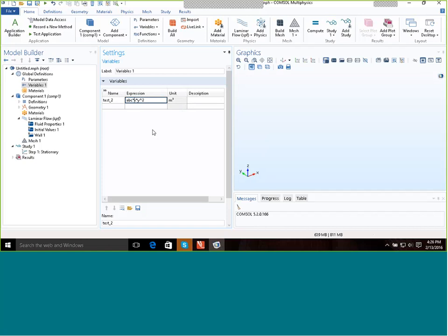Now, COMSOL is not going to know what ABC is unless I accidentally pick something that's an internal variable. And so what is it going to do? And you can see it gave this little orange color, which means COMSOL is confused, but it will keep going. It's kind of risky to keep going. You can hover your mouse over there. It says unknown variable ABC. So it didn't know what ABC is. That kind of gold color, orange gold color, it's kind of like a warning.